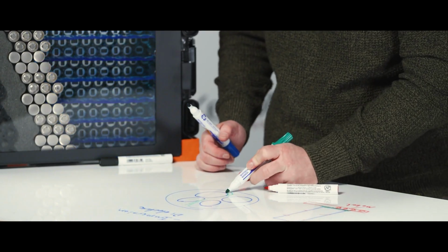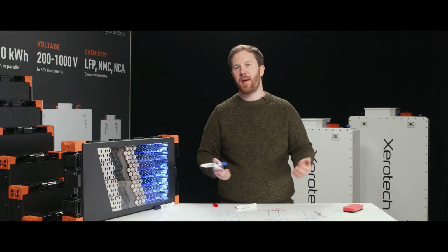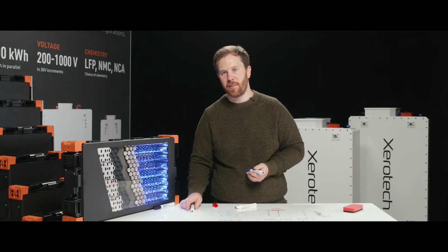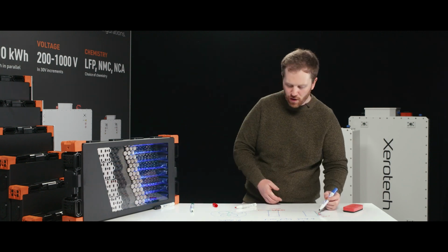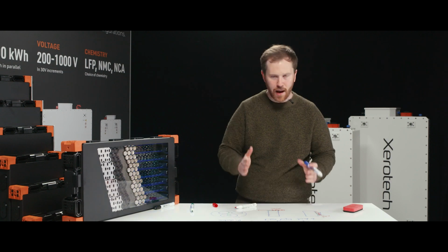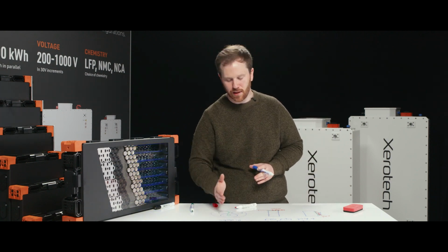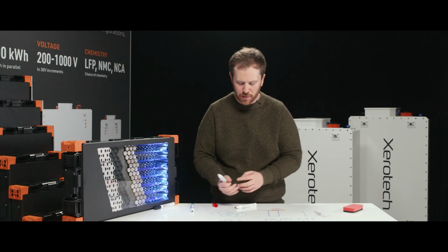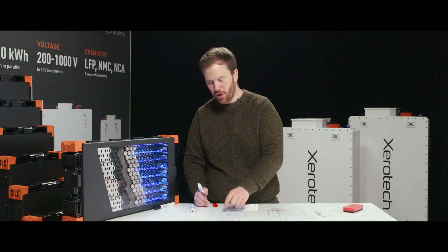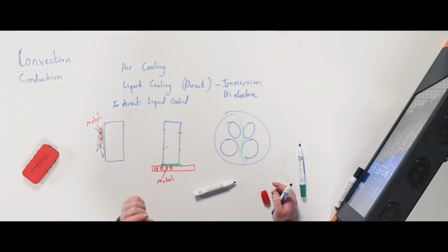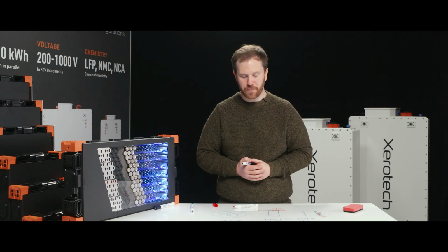So you basically get perfect angular contact around the cells. This was a big problem, for example, in the early Tesla Model S days, trying to get an extruded aluminium duct in between the cells and have a squishy rubber thermal interface material to contact the cells. If you've got a cooling system that can inflate and fill all of the space perfectly, ensuring perfect contact area, while also being extremely thin, you end up with a very good cooling system.